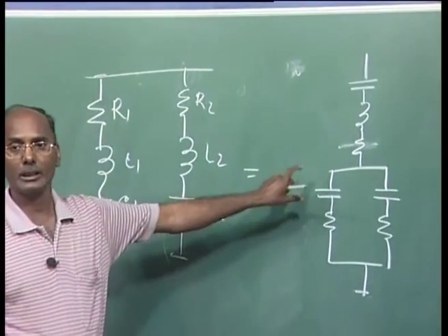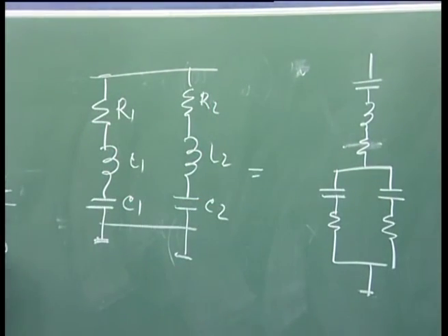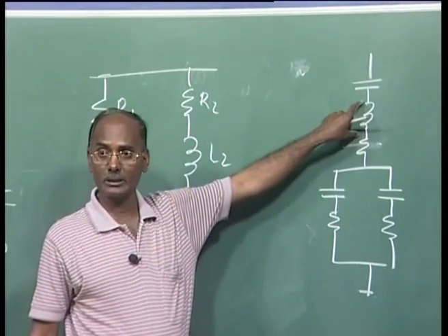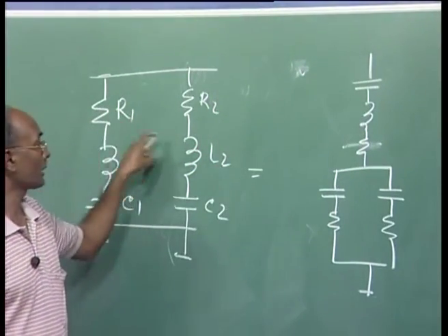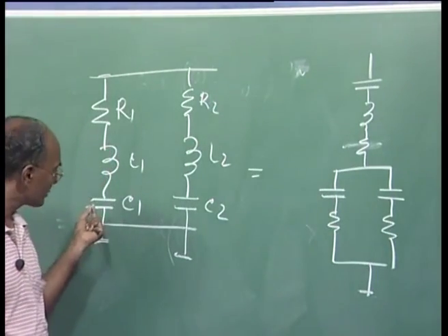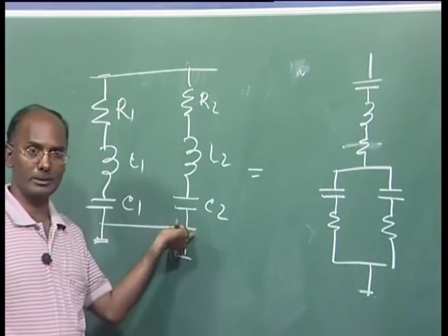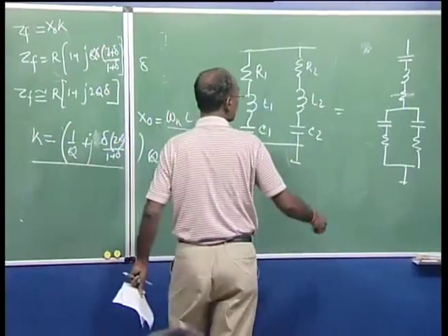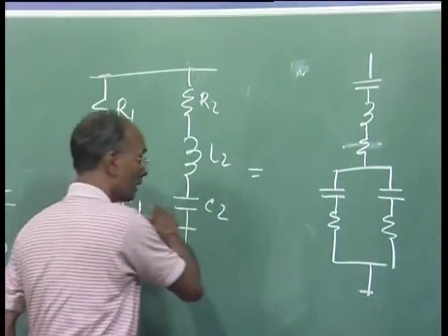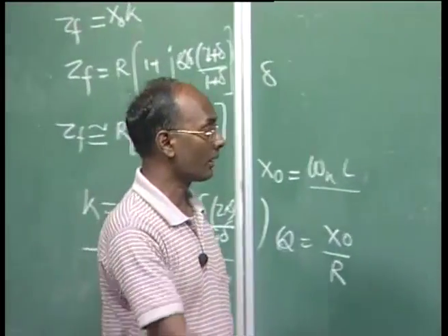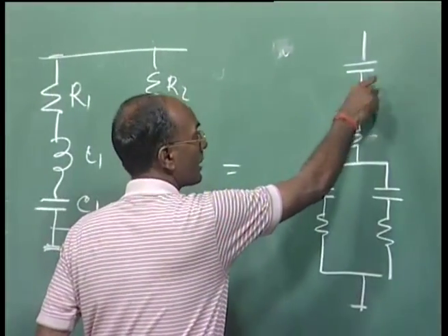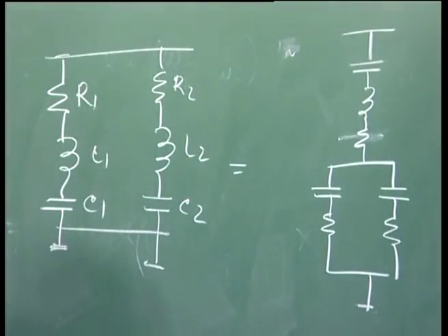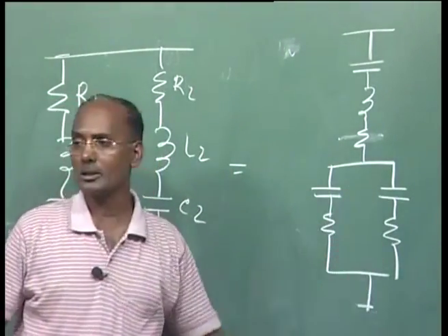So this is a second order, another double tune filter. In this case, you are using only one inductor, whereas here you are using two inductors. So this is a single tune two filters; here, single double tune filters are there. This is more advantageous compared to the other, because only one inductor is sustaining the complete voltage, so we are minimizing the cost. But no doubt we are putting some capacitors and resistors in the circuit.